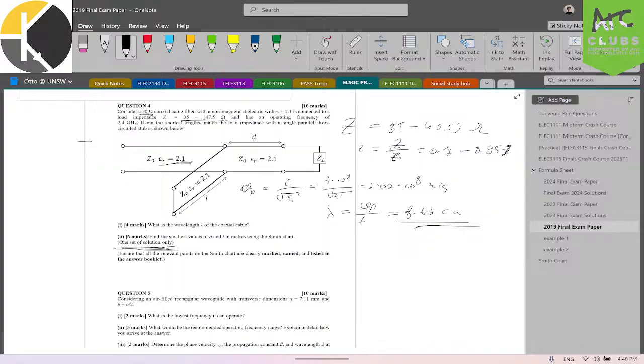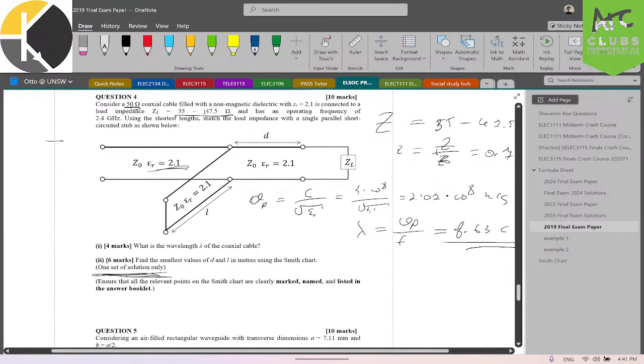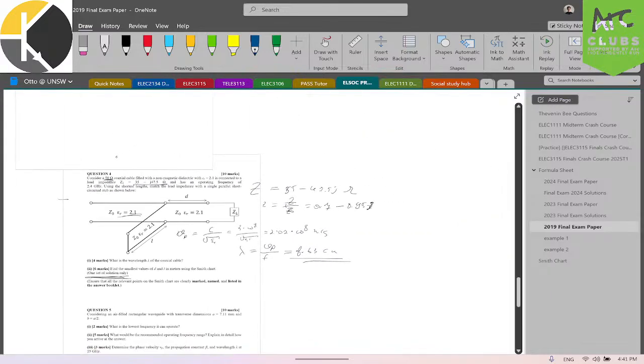You can make your cable sections longer by half a wavelength and still get valid matching. It's most convenient to just find one simplest solution. Sometimes you have two simplest solutions, which you need to decide between, using shorter cables, but not in this case. Yeah, let's go to the Smith chart.